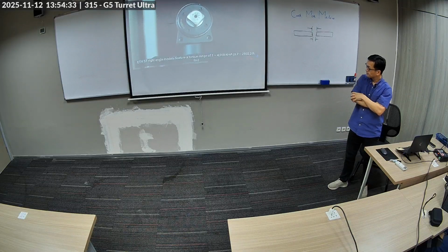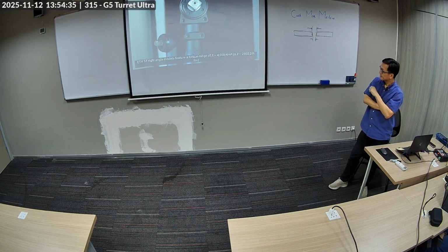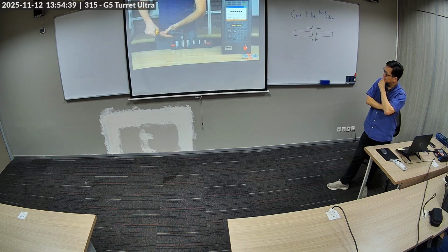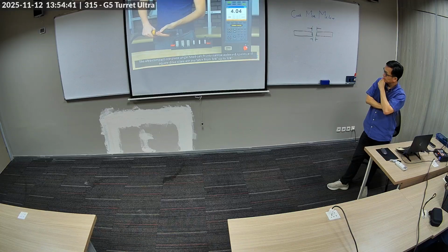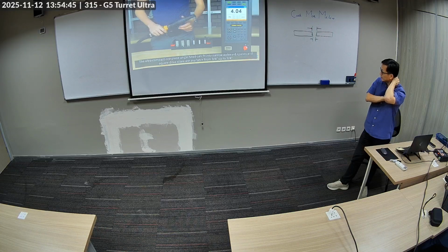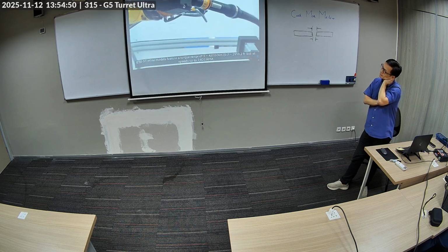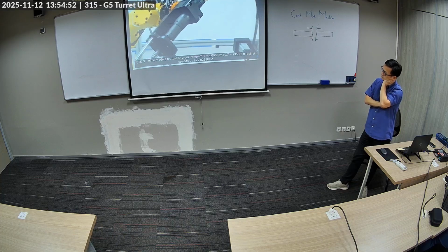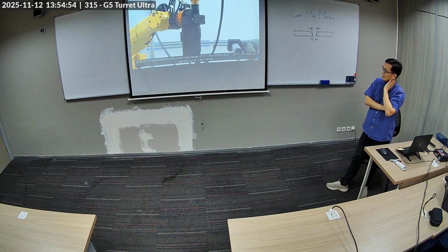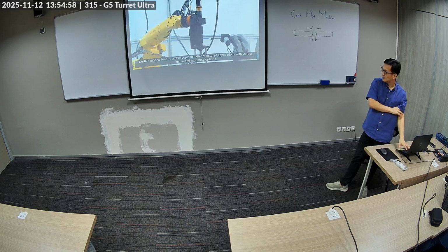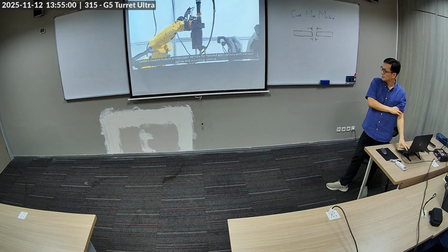ETV ST right angle models feature a torque range from 1 to 4,000 newton meters at speeds up to 2,390 RPM. The ultra-compact one-piece angle head can fit into narrow, awkward spaces, and square drives are available in 3/8 inch up to 3/4 inch. ETD ST inline models feature a torque range from 1 to 4,000 newton meters at speeds up to 2,825 RPM. Certain models feature a telescopic spindle for fixtured applications with various line and mounting options.